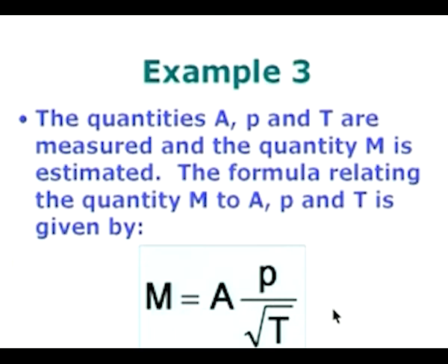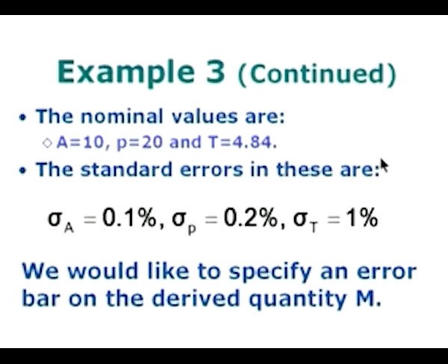Let me just digress and tell you what we are trying to do, what this problem is. In measuring fluid flow, sometimes we use a sonic orifice, and in that case the mass flow rate of the gas is given by some constant which is obtained by some kind of a calibration process multiplied by the stagnation pressure and the stagnation temperature upstream of the orifice. So, this is an example which is taken from fluid flow, and let us see what we are going to do.